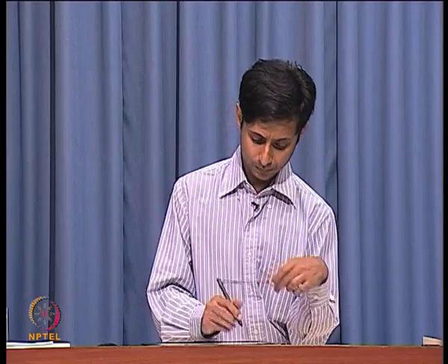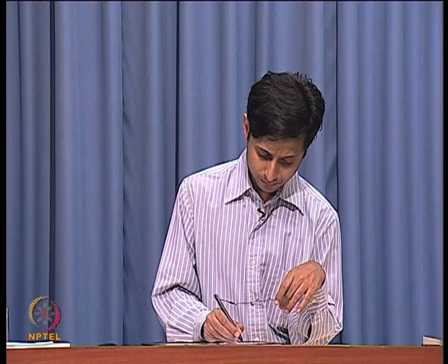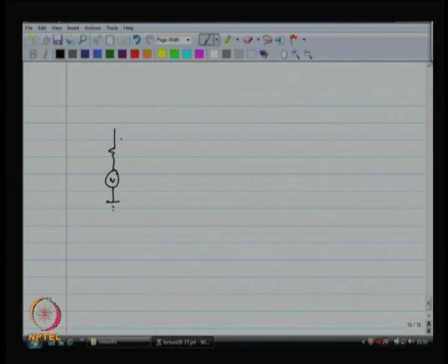You have heard of gain bandwidth product, right? If I somehow decrease the gain, I can increase the bandwidth. That can be done by using principles of feedback. So, this is a very common circuit, and what I propose over here is, let us put feedback.